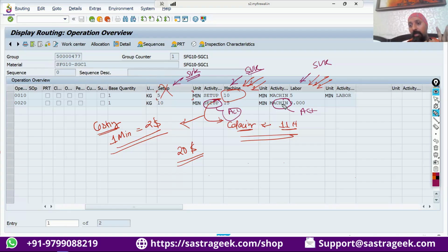In between, we have a question. Can we add overhead cost for electricity, lubricants? Yes, electricity and lubricants can also go into the overhead cost. Overhead cost is just defined as a percentage, like 5%, 10%, 8%, and it would be there everywhere. Each and every thing you cannot monitor, right? There is a supervising staff, there is an HR staff, you have a general manager. All of their salaries also contribute to bringing the product out, right? So that cost also needs to go in. Yeah, that is also the cost.